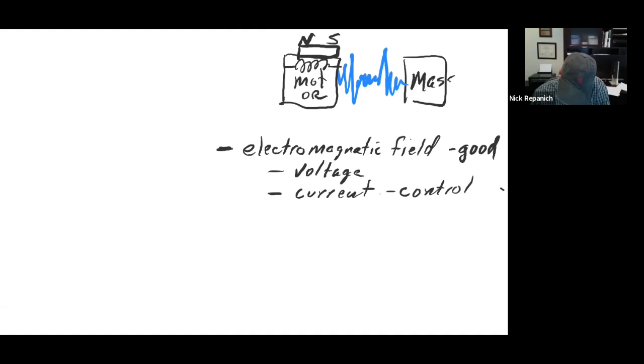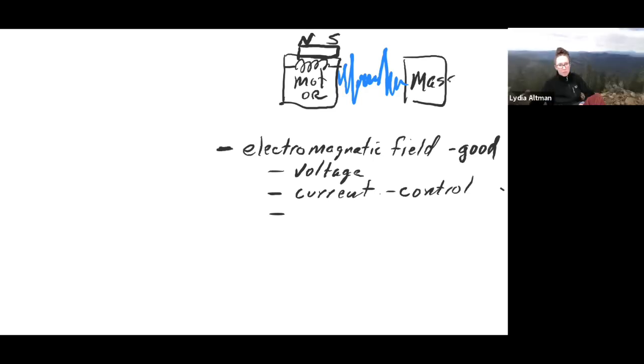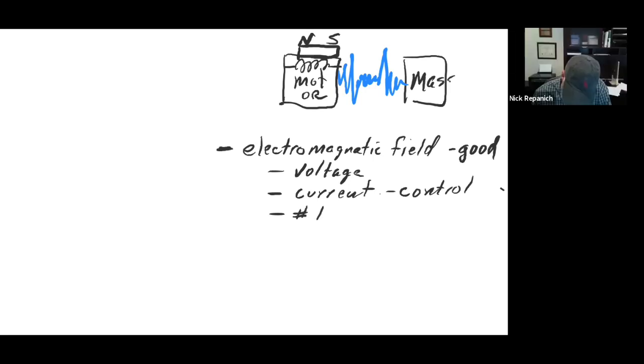And one other thing that the motor manufacturer is controlling: current and voltage. Here's the voltage and current you need to give to this motor. There's one other thing when you've got a winding that controls the strength of the magnetic field: the number of turns, or coils, however you want to put it. How it's wound. The more windings you put in this thing means either big wires and fewer turns, or little wires and more turns, and more turns is more mass.